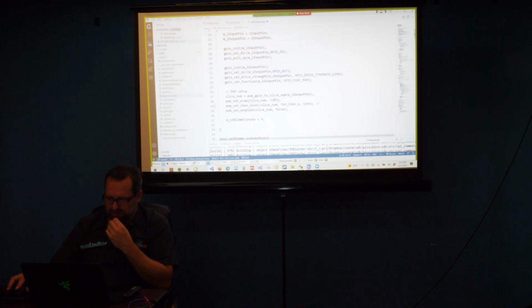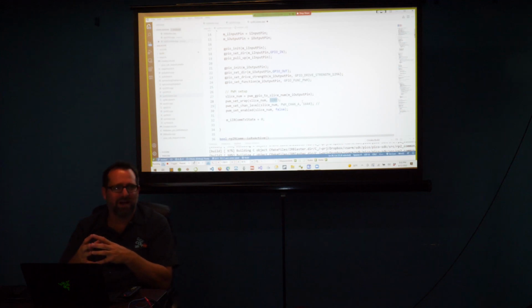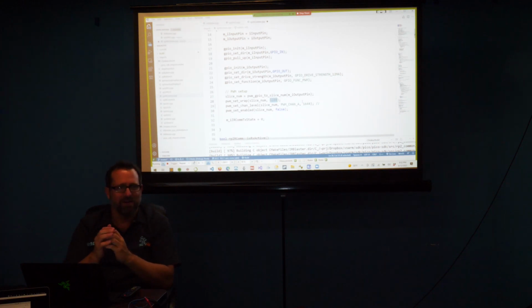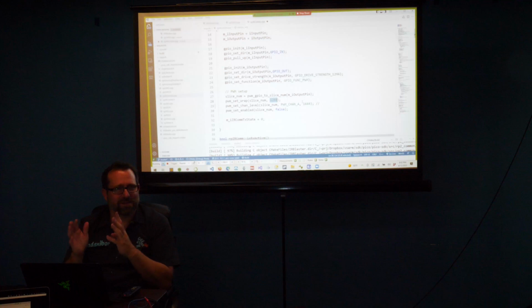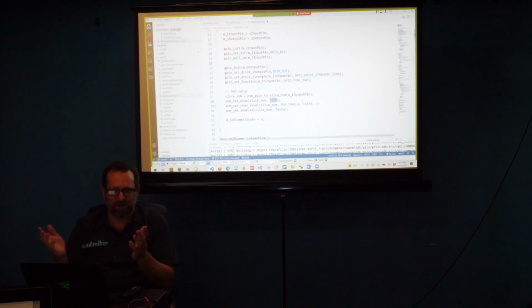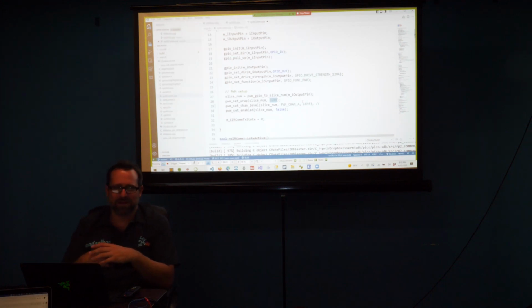So this number is basically the default clock rate. If you don't underclock or overclock, the Pi Pico clock rate is 125 megahertz, which is really confusing because they always talk about how it's 133 megahertz in different areas, but I can tell you it's 125 megahertz. And 1 over 125 megahertz is 8 nanoseconds, so each system clock is 8 nanoseconds.